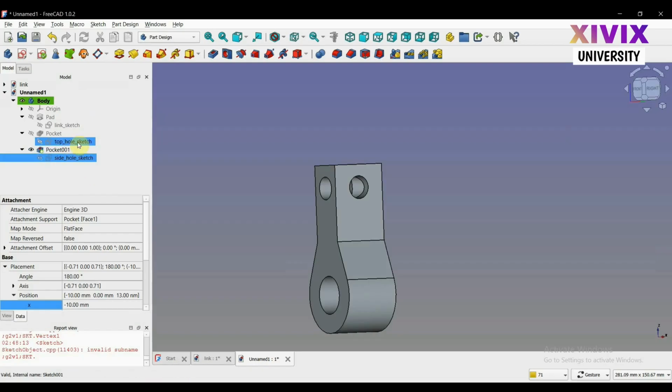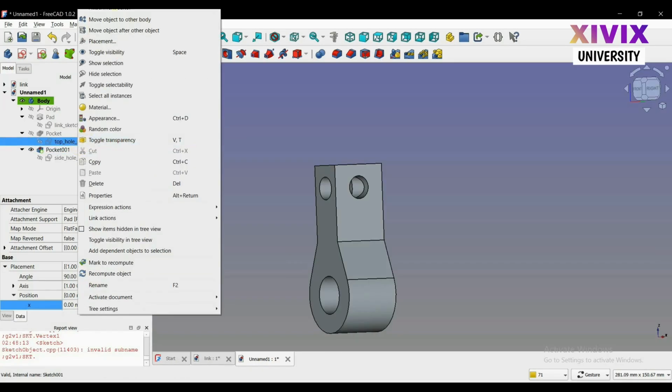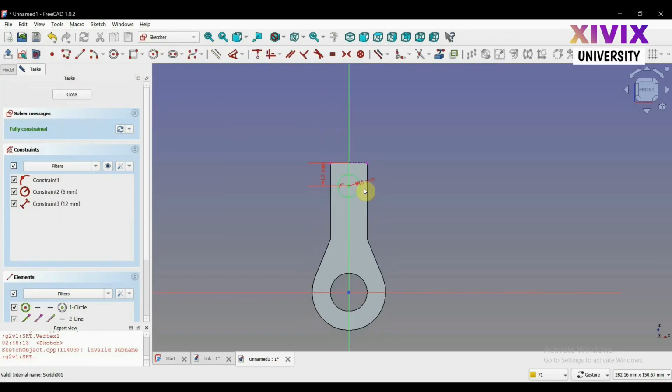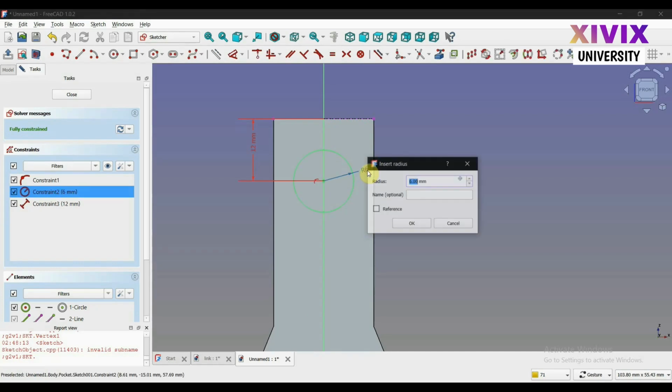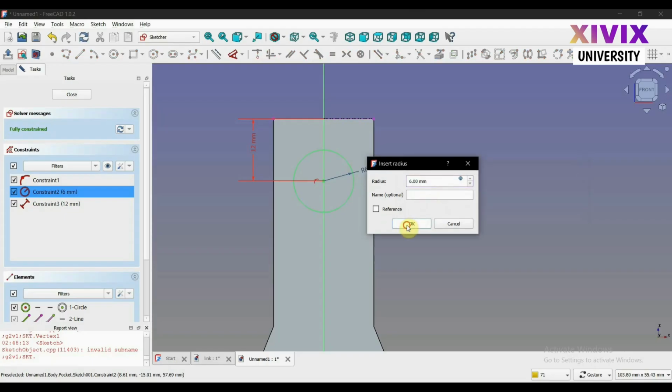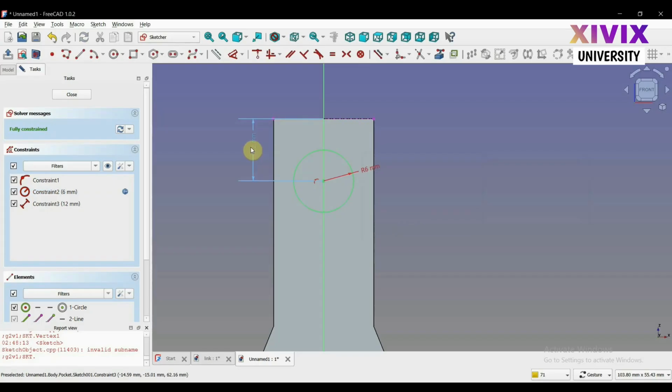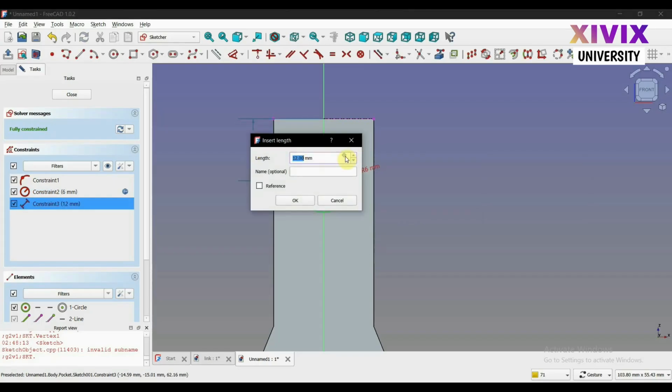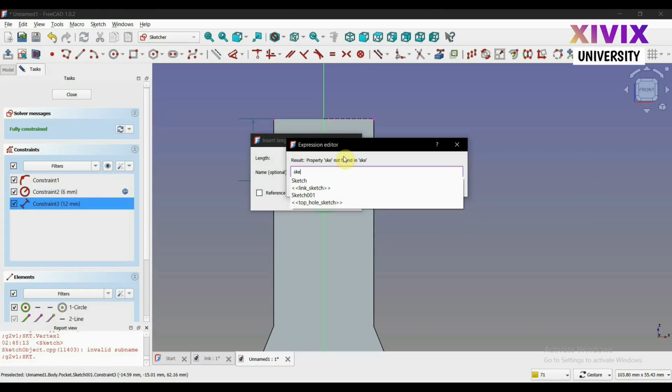The same logic will be applied to this circle right here. Everything is the same over the expressions editor. Go to link sketch, constraints, main driver. You do not necessarily have to search for the original sketch where you have defined the master driver, since we're already in the master driver, but it will not be throwing any errors.